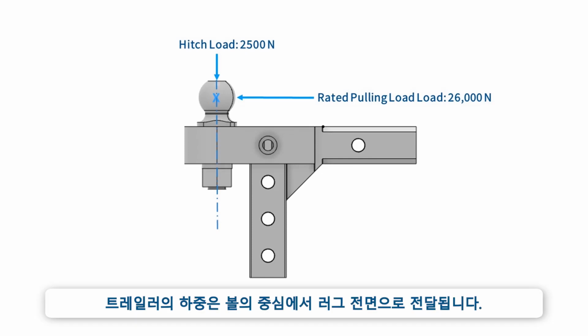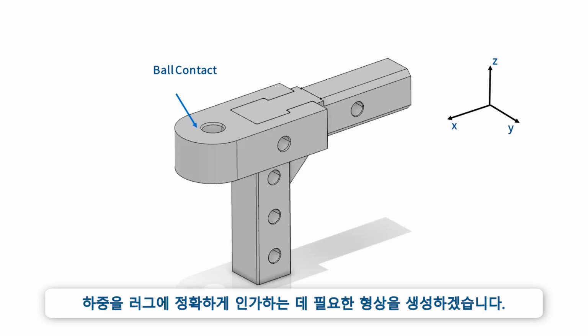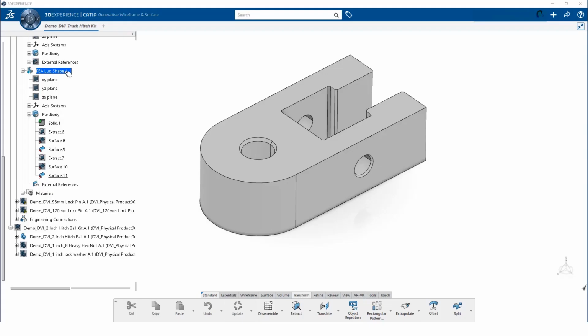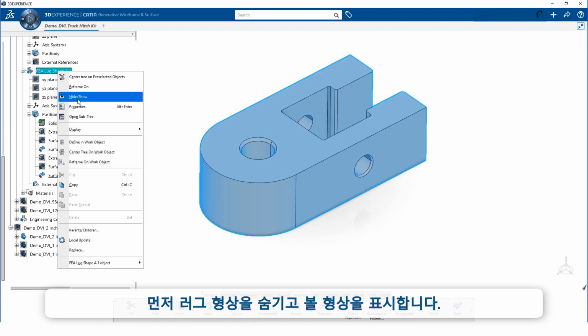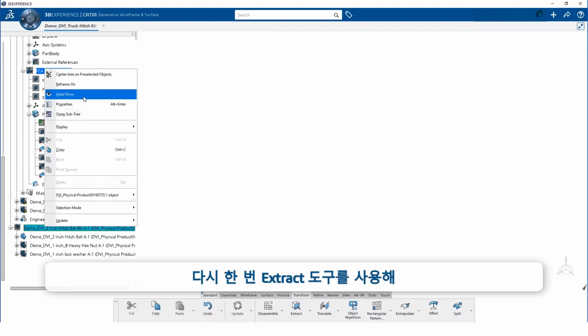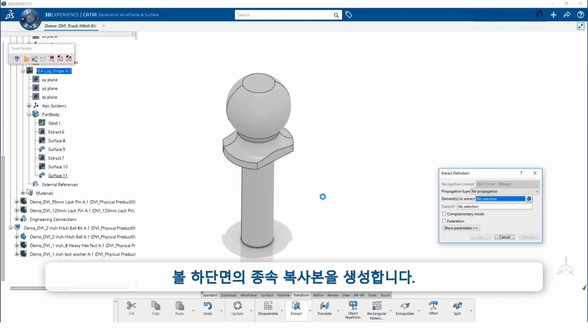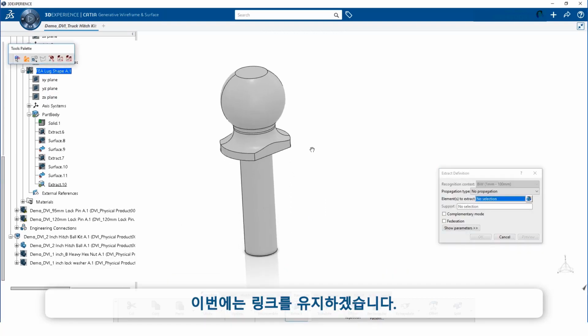The trailer loads are transmitted from the center of the ball to the face of the lug. Since we are not modeling the ball, we will create the geometry required to accurately apply the loads to the lug. First, we hide the lug geometry and show the ball geometry. We will again use the Extraction tool to create a dependent copy of the bottom face of the ball. We do this by keeping the link.